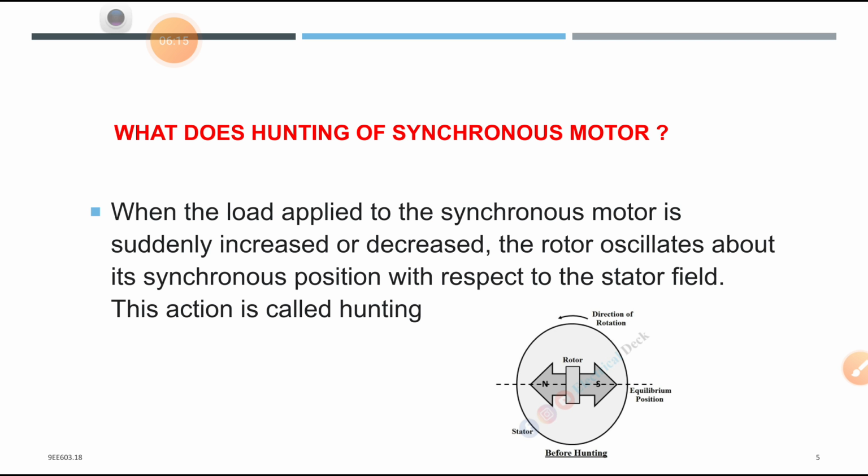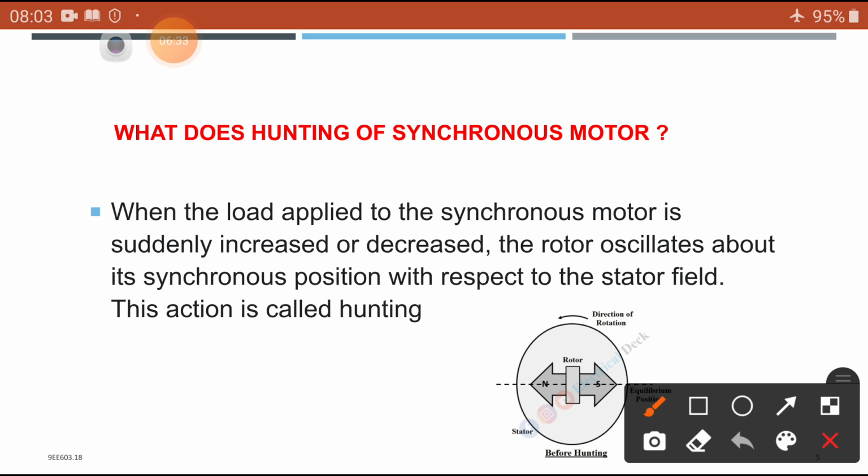When the load applied to the synchronous motor is suddenly increased or decreased, the rotor oscillates about its synchronous position with respect to the stator field. This action is called hunting. This is the definition and the total meaning of this.